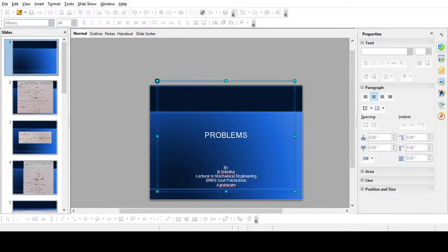Linear strain, the longitudinal strain, is the strain which is produced along the direction of the force. It is sigma by E, equal to delta L by L. It is simply the elongation, 0.0045, by the actual length, 75 mm.